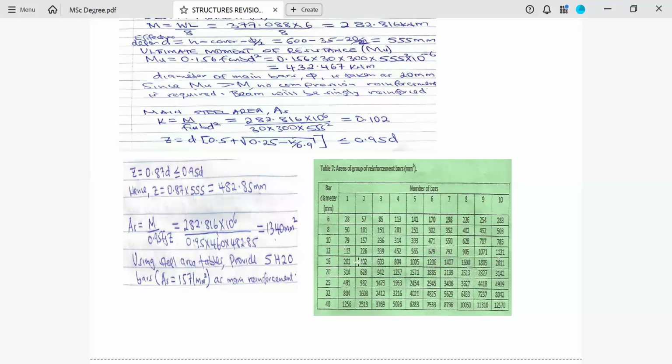someone implementing the project to have the 7 bars. Maybe concreting will be difficult. So sometimes we can maybe move and adopt like maybe 1473. Those are 25 millimeter diameter bars. Now it will depend when we arrive at this point. For our case of learning, let us stick to our 20 millimeter, giving us 1571. But in reality, sometimes it might not be the same. Why? Because of practicality issues.